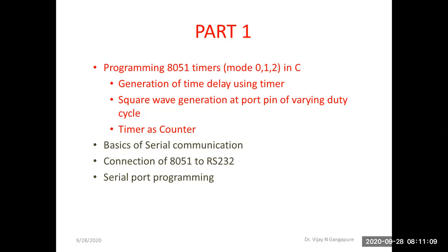And timer 0 and timer 1 are associated with their own timer registers, that is TL0 and TH0 for timer 0, 16-bit, and TL1 and TH1 for timer 1, again also 16-bit.